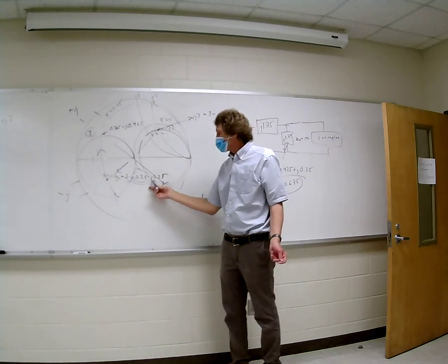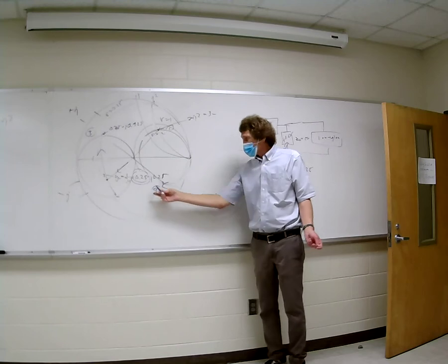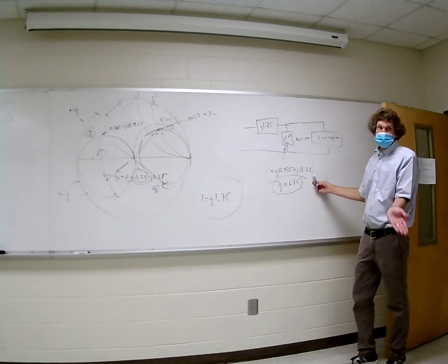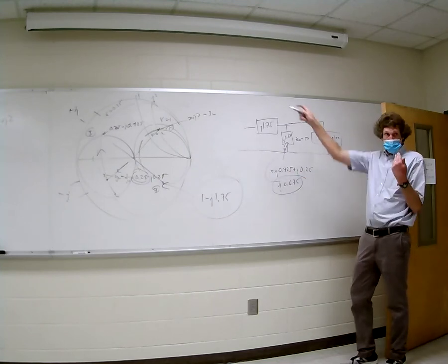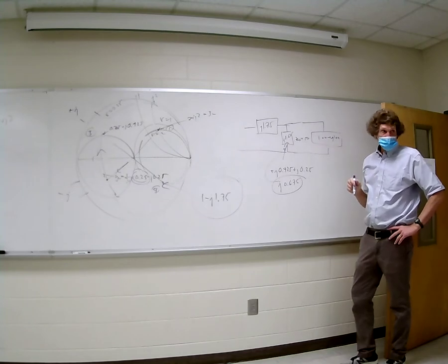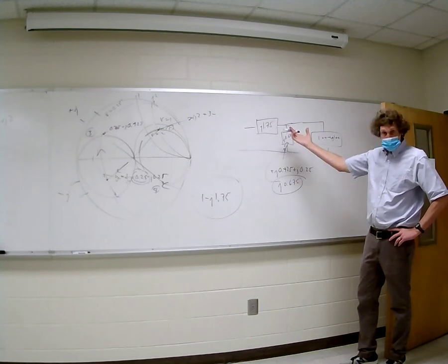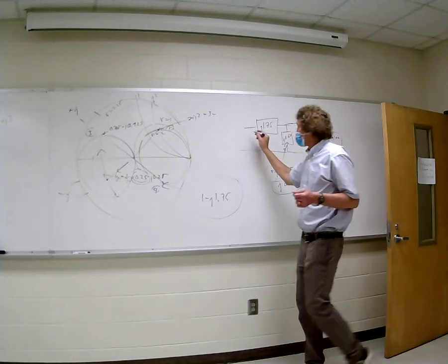I had to go 0.25 to get rid of this minus j 0.25. So my values here would be 0.25, that's where I started. I add that much, I'm back to 0. Then when I add 0.425, now I'm right on the rim there. You with me? Yeah, I'm good. So now when I'm on the rim there, I add the impedance. It's positive, this is positive, and now I'm done.